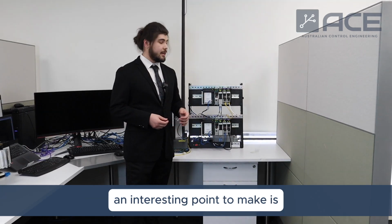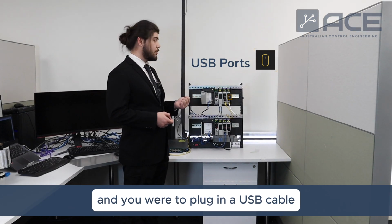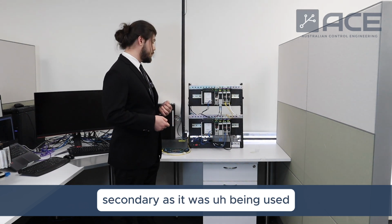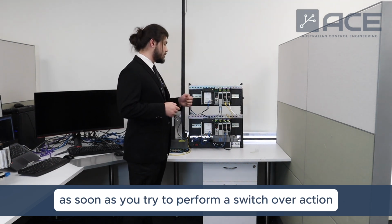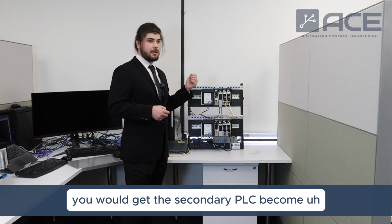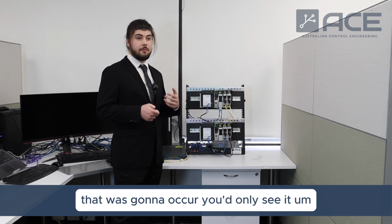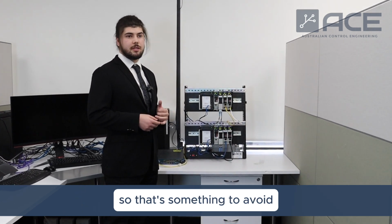Now, an interesting point to make is the USB ports on these Ethernet modules. If you have a synchronized system and you were to plug in a USB cable to one of the ports on the secondary as it was being used, no disqualification would occur, but the issue would be as soon as you try to perform a switchover action, you would get the secondary PLC to become disqualified, and it would not actually take over control upon switching over, and there'd be no indication before that was going to occur. You'd only see it when you actually tried to switch it over. So that's something to avoid.